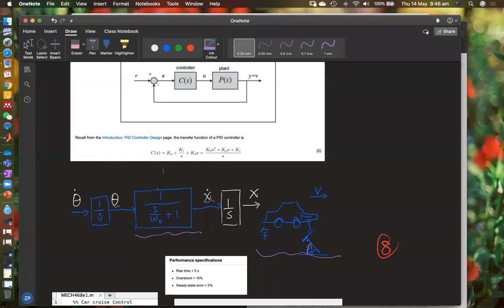You can step to the bottom and make a very large theta, and the speed will change fast. However, something we have to remember is that this has a certain limit. You can't go too far because you can only put your foot down completely. That's the limitation of the power of the car. So you have a certain limit here, and this is something I'm going to mention a bit later. This is important when we design a controller. Very often we ignore this and forget about the limitation of our power. We just say a big controller like that is going to achieve our goal. However, our controller actually has certain limitations. You can't really do that with an ideal controller. I'm going to mention that a bit later.